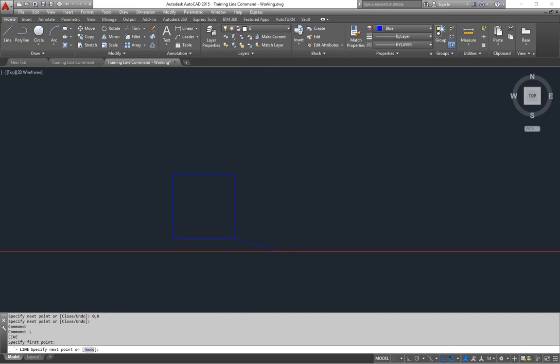So now this wall is going to be 20 feet wide. Instead of using absolute coordinates, which I could, which would be 30 feet on the X and 0 on the Y, this time let's activate the ortho mode, which is F8. So now we're going straight in this direction. And when you're headed in that direction, you can just tell it how far you want to go. So 20 feet, enter, and it shoots off that direction 20 feet.